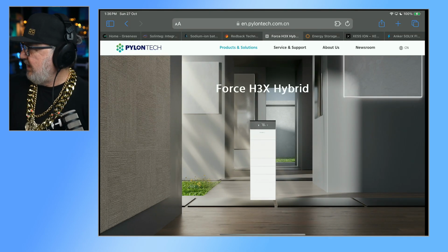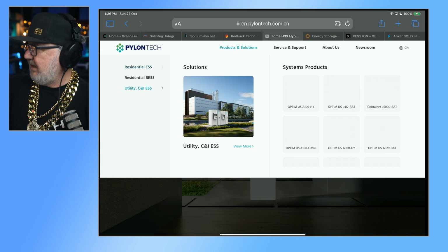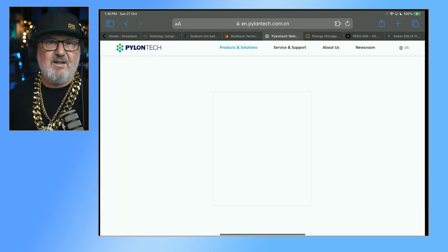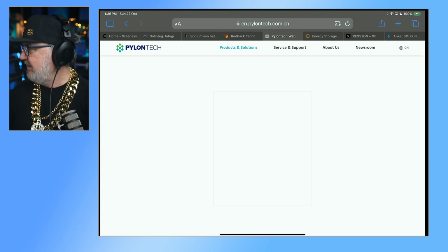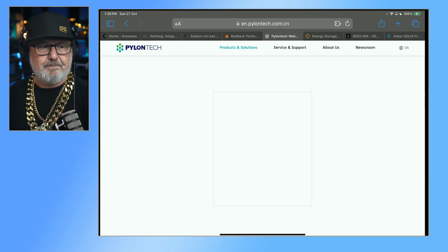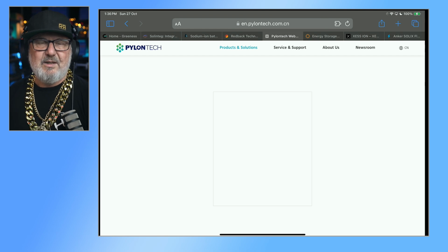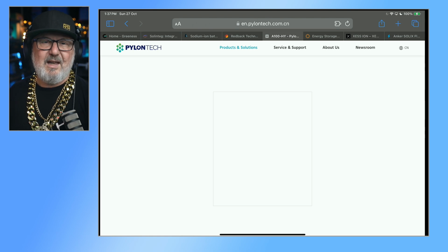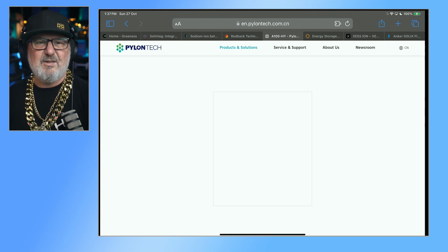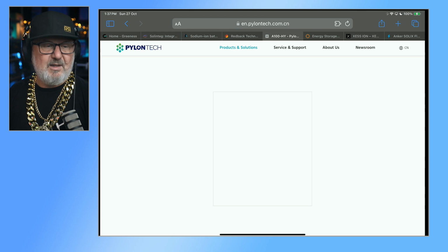They were also showcasing their CNI systems, and so they've got some nice big CNI units there. See if that's going to come up in a sec. So for those who are not familiar with the acronym commercial and industrial, basically we've kind of got 3 market segments. We talk about residential, people's homes, CNI, businesses, and that means it's generally behind the meter systems, and then utility, which is in front of the meter. And utilities generally large scale, megawatts capacity.